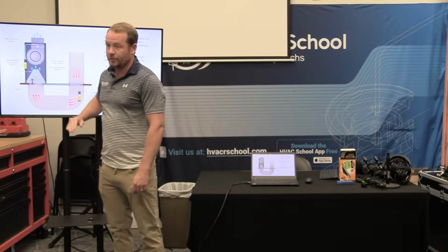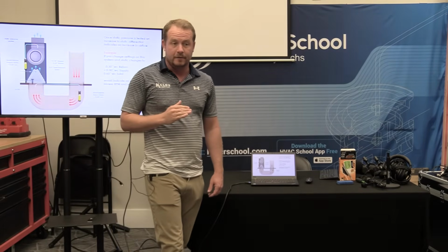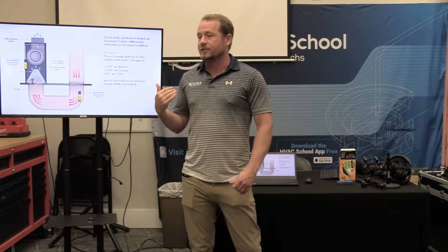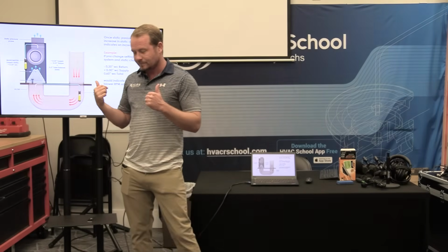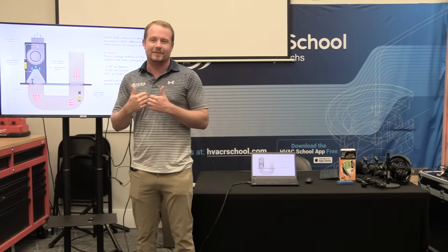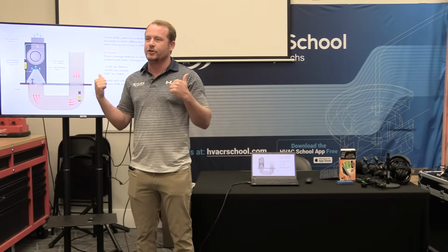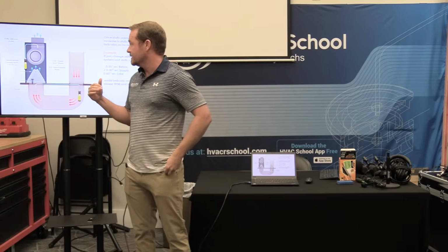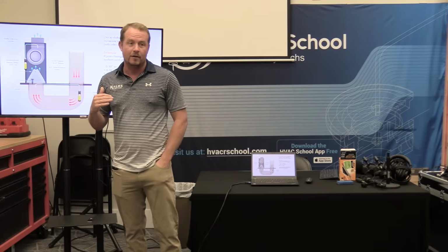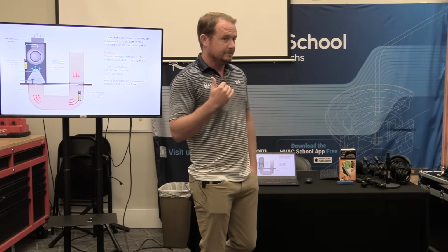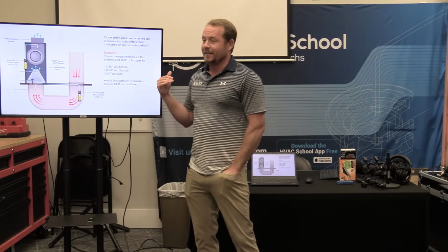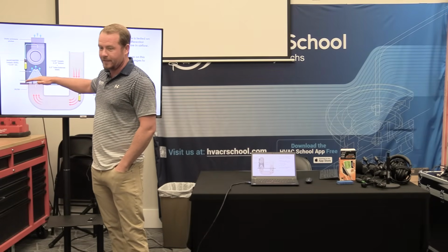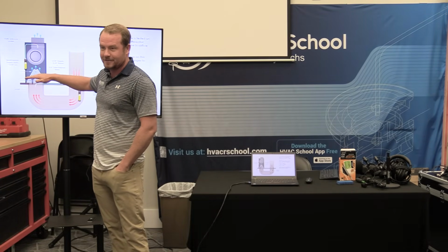But if we measure below the filter and that filter is really clogged, that's going to make it look like we have better static pressure than we do. There's an infamous video, I don't know if you guys remember this, where a guy was showing how with a pleated filter, a really high MERV filter, the system actually has lower static pressure with a more restrictive filter, right? He was showing that it should even work better, but that was because he was measuring below the filter rather than above the filter, and that makes a big difference, right?